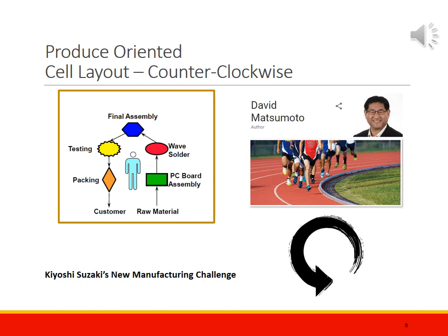I don't know this for a fact, but I do know that when you're in a manufacturing cell and you're right-handed, the best use of your ability to grab a part and place it in a fixture happens with the hand that has the most dexterity. So in a lean one-piece flow cell, you grab the part from your right-hand side with your dominant, highly agile right hand, and you're able to set it in the fixture very rapidly.